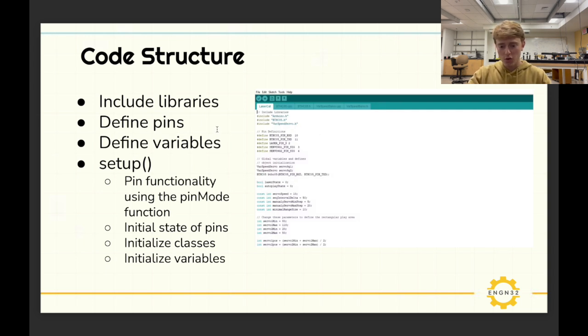All right. Also defining pins. So you'll give pins a name. For example, switch in. It might be a name for your pin. So you'll put hashtag define, switch in, and then the actual number of that pin that you will find on the pinout, so the Arduino knows what values it assigns to what pins.